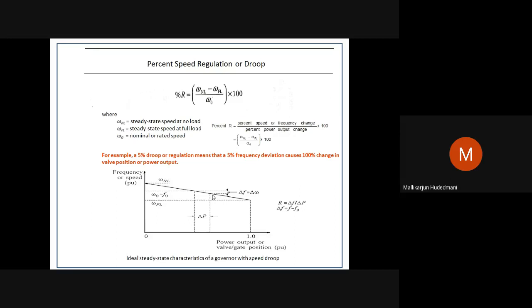There is no doubt the machine is developing the power and giving it out, because in this study it was supplying 50% of the capacity originally, and there is a shift in load. Let's say a small extra megawatt is loaded, and frequency has fallen. Still it has capacity up to 100%, but the frequency is compromised.